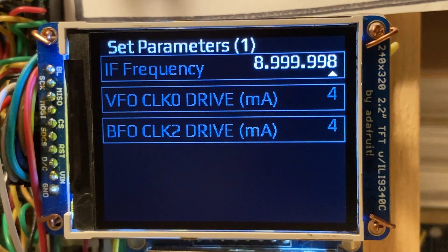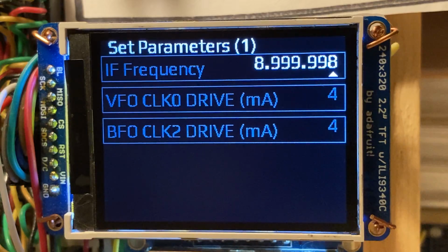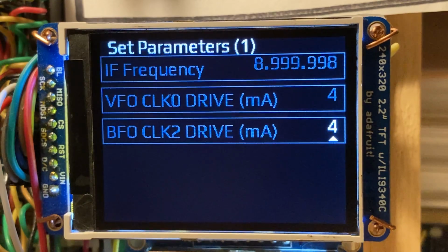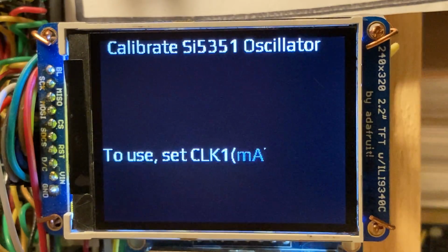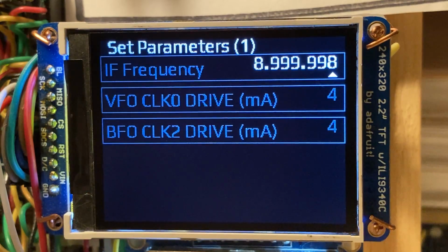You have several parameters here that you can set by turning the rotary encoder, but to get to the next parameter down, you would have to press the GUI page, and it would step down, but then you couldn't go back up, so you had to go all the way through all your GUI pages again to get back to what you were working on to make the change. That was just a limitation of the way I originally set up the code, and it was sort of boxed in; that was the only way I could do it.